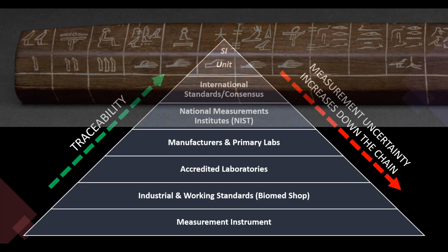And then you have your SPRTs, your special platinum resistance thermometers. Usually with those, you have a much wider temperature range with much tighter accuracy. This is how we get into the millikelvin measurements, but your response times are closer to 4 or 5 minutes for your measurements. So again, we're not looking for really quick measurements. We're looking for how stable it is over time.